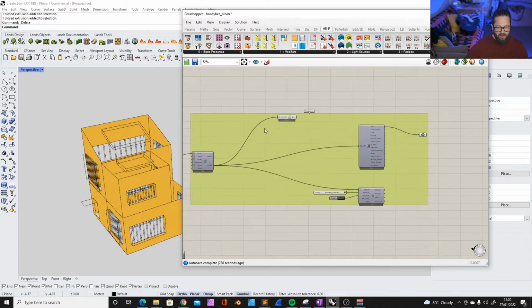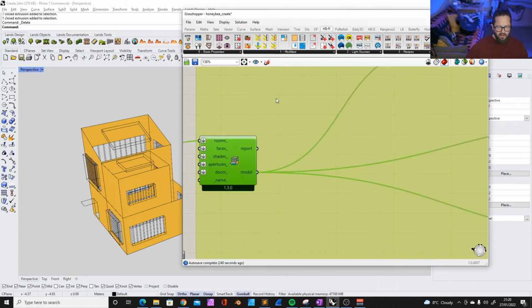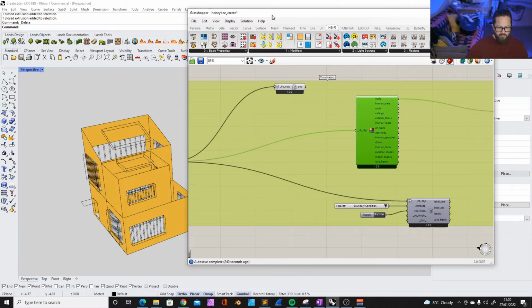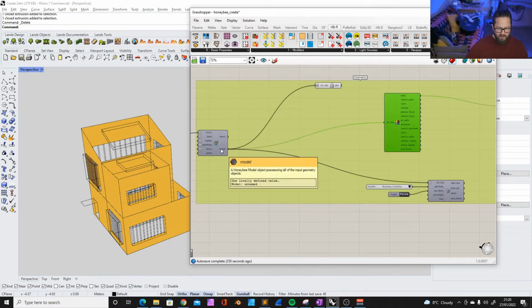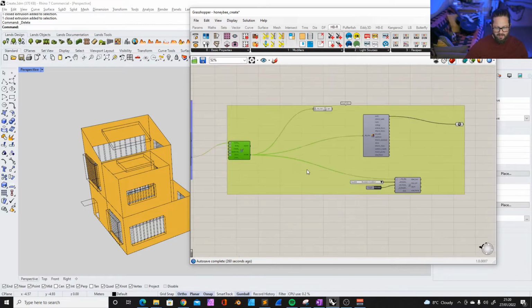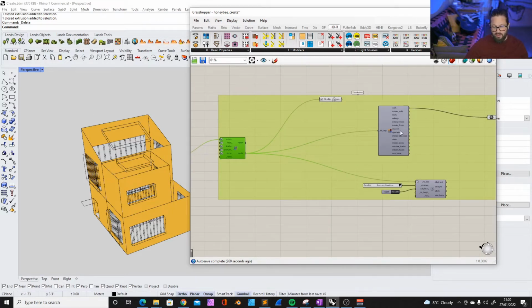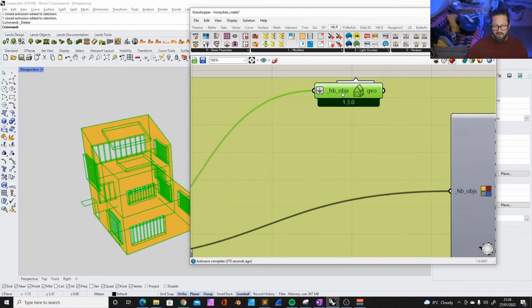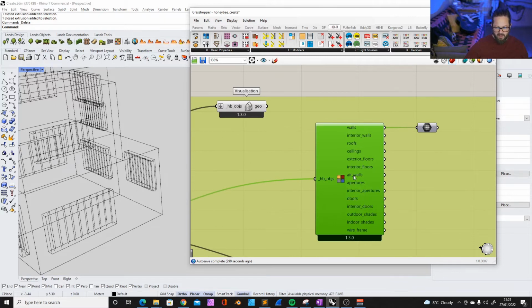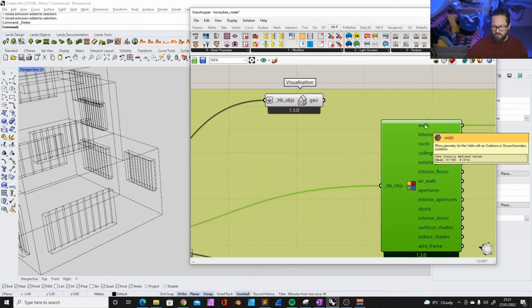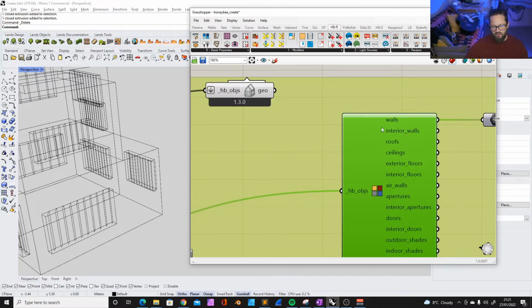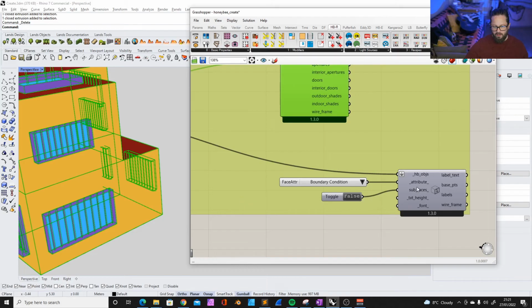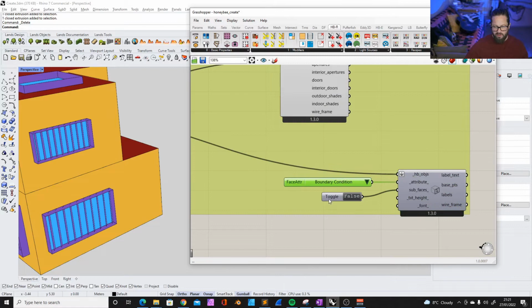And first I just showed that there are ways to visualize, because the thing is, if you try to visualize it with, let's say, Grasshopper standard materials and so on, it's going to be tricky, because this is not a typical mesh. It's now a different type of geometry. There is a geometry with data attached, and if we want to visualize it here in Rhino, it needs to be retranslated to something we can actually look at. In that case, that tool does it for us. It just visualizes the wireframe of that building. And then we feed the object in, and every object, walls and so on, they are meshes, but they have more data attached, and we basically just extract the mesh from that data set to make it visible. And yeah, there are other ways to visualize stuff. You can visualize by attribute and so on.